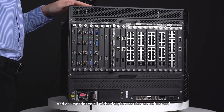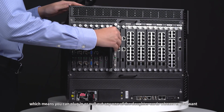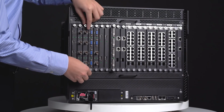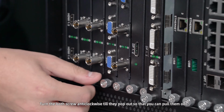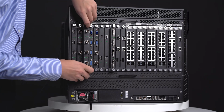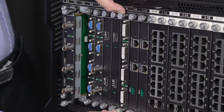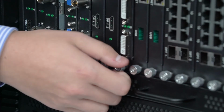And as I mentioned, all of the daughter cards are modularized, which means you can plug in or pull out any one of the daughter cards whenever you want. Let me show you how to do this. For example, this one. Turn the bolt screw anti-clockwise till they pop out, so that you can pull them out. And on the contrary, if you want to plug in, you're supposed to plug the card to the end and then press the screws a little bit before turning them clockwise.